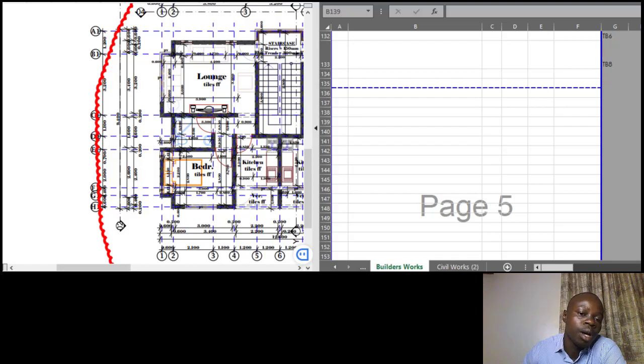Welcome. When you want to estimate walling, the rule for estimation, that is from the standard methods of measurement, tells us that we need to do it in square meters. So what matters most is how to get the center line, which we had learned previously in one of our sessions, but it will be reinstated here, or let me say emphasized, so that those who are new to the channel will be able to get it better.